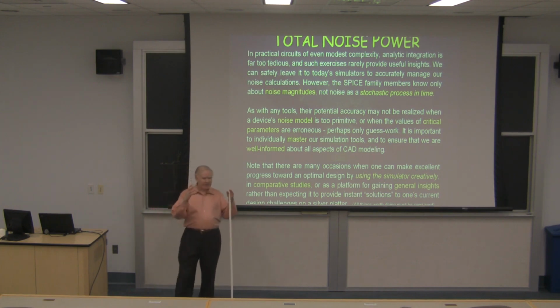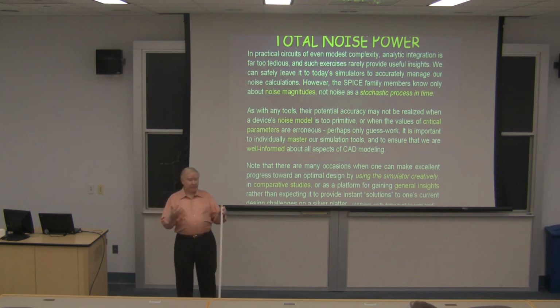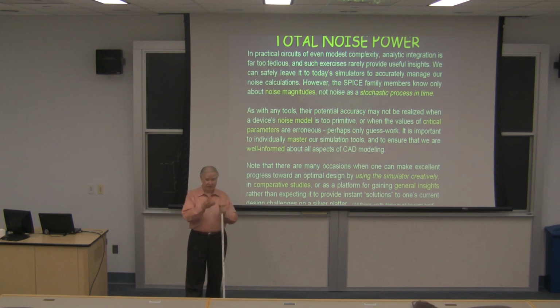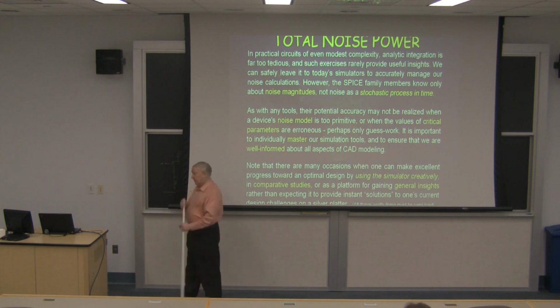because built into a simulator is hundreds of thousands of person hours of thinking about how devices work, of modeling and so on. In many cases, some of the limitations, if you're using TSMC as a process, or another foundry process, you may find the models are not only pretty primitive and incomplete and not up to date, but the parameterization of those models is also incorrect. I mean, there's two distinctions here. There's the equations that define current transport in a device, and then there are the numbers attached to those equations, the coefficients, if you like, and they can often be very, very far off from the truth. The only way of getting around that is to make your own measurements, or have your own group make the measurements, and we're lucky in having a CAD group that does some very good characterization work. So those are some of the limitations of simulation.